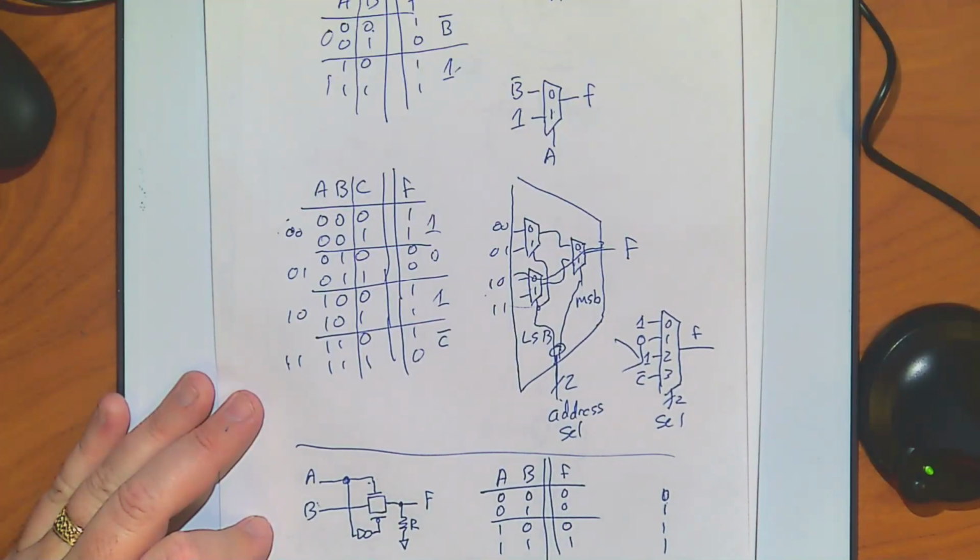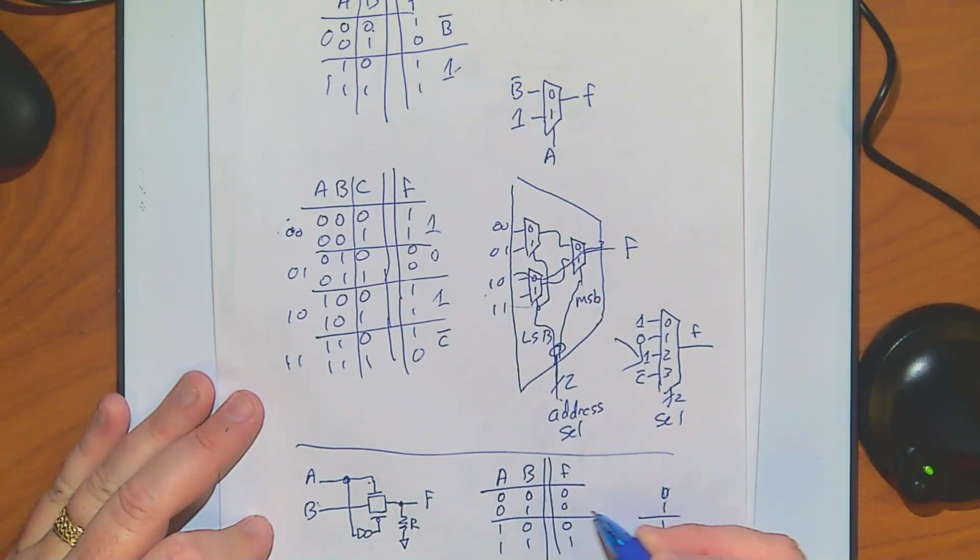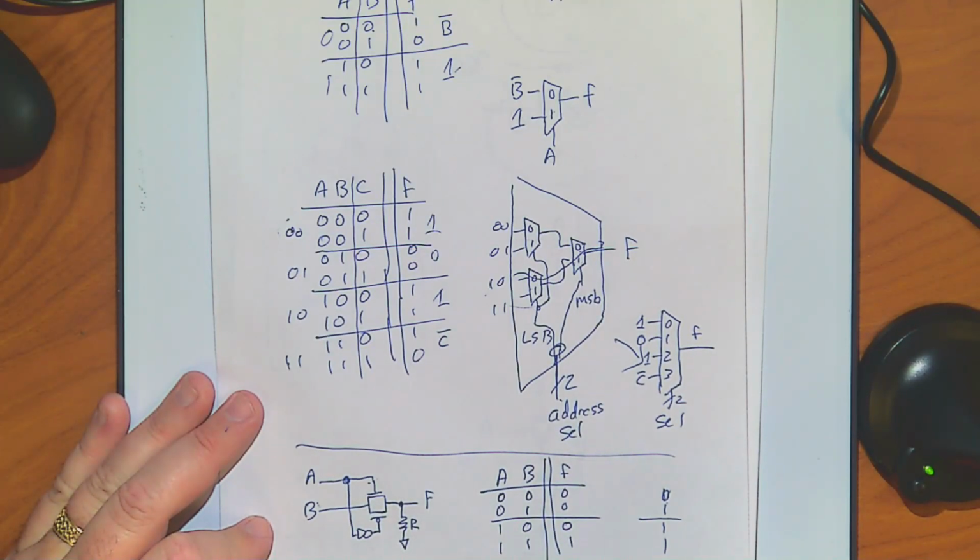That's an OR. You could break it into pieces. I want to pass through B on that, so I can just flip A, and then it'll pass B through. So if I put A bar in instead of A, I just put an extra NOT gate there, or flip the NOT gate to the other side if you want to think of it that way. That would let me pass this one through, and then I put a pull up resistor. An instant OR gate.